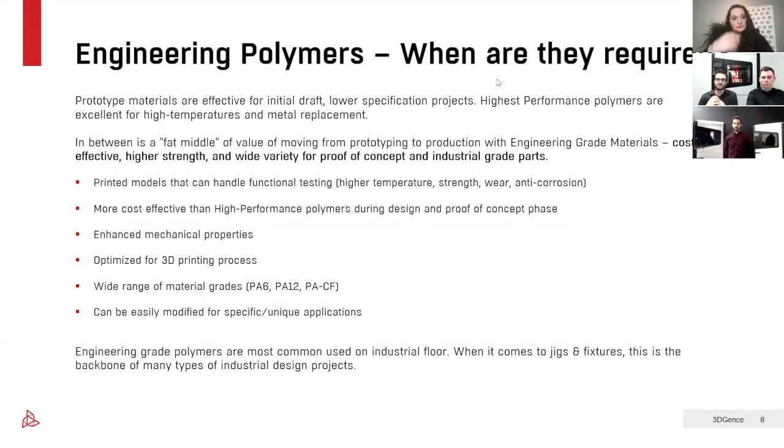Also worth mentioning, there is a multitude of different grades of those materials. Just considering polyamide, there are really a lot of different grades. Like the three that we're mentioning here, PA6, PA12, or PACF is just the tip of the iceberg. There's polyamide 666, 669, 618. It's literally pick and mix sometimes. And it's all driven by the application in the end.